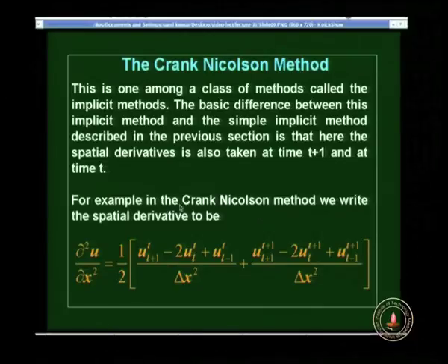Okay, so this method is again an implicit method, in the sense that the right hand side of the equation del u by del t equal to k del square u by del x square is still a function of temperature at time t plus 1. But now it is a mixture of the times t and t plus 1. So again we could use the same scheme.